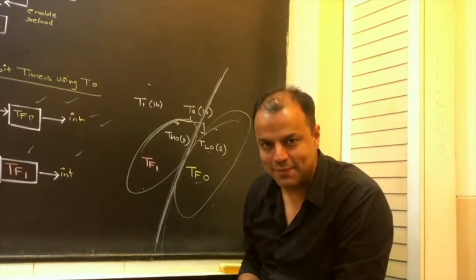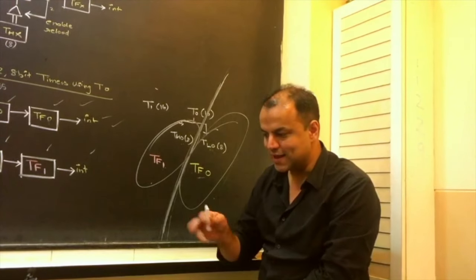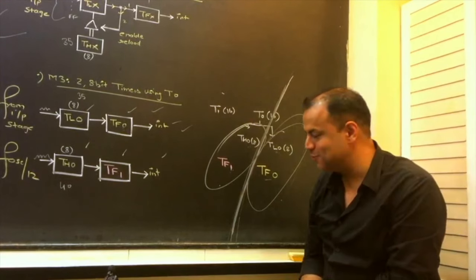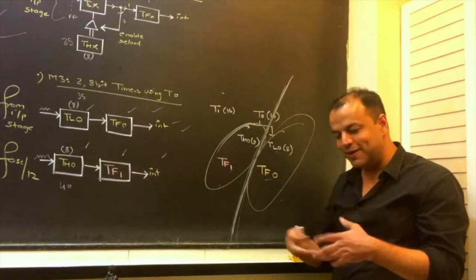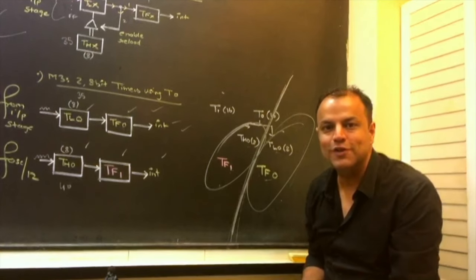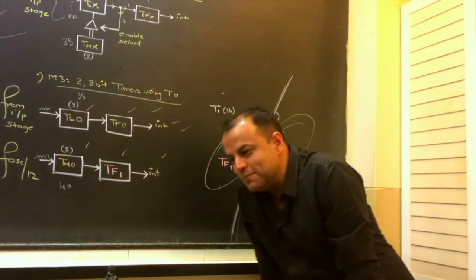But what has happened now? Can timer 1 count? Yes, it can count. Can it overflow? Yes, it can overflow. Can it inform the processor? No, it can't. That means it will count by itself, overflow within itself. It will never even tell the processor it has overflown because there is no flag remaining to report this. That is mode 3.